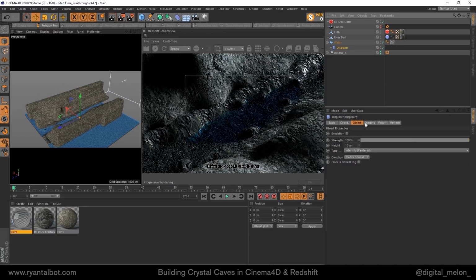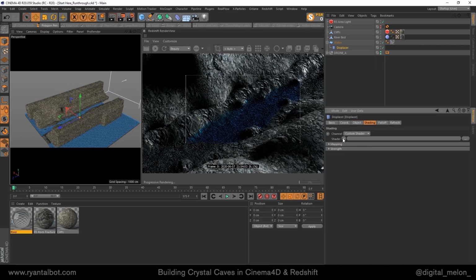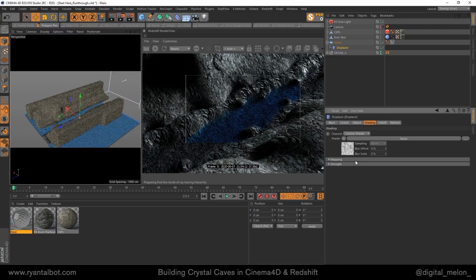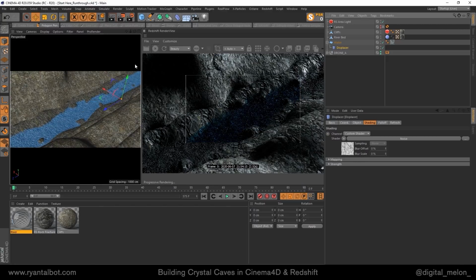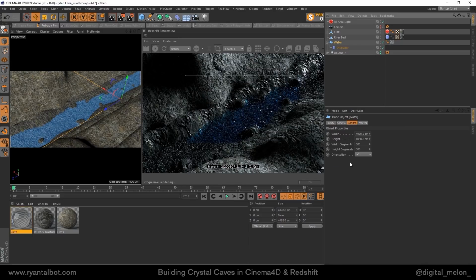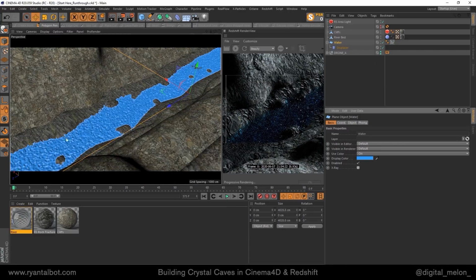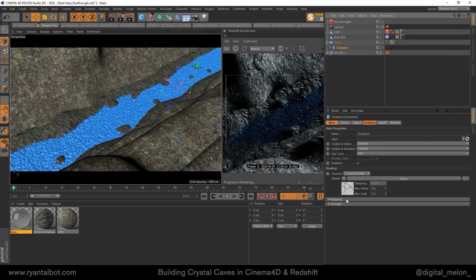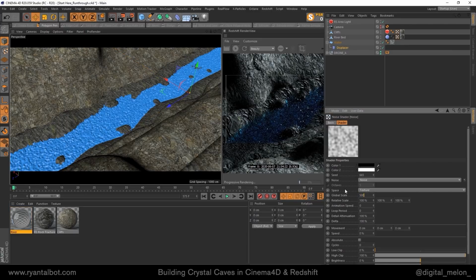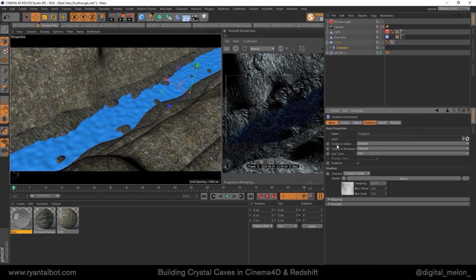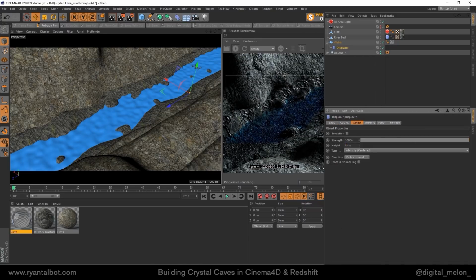And so this is a pretty simple and standard way to do some basic animation on your water. You essentially just drop a noise in here. And let me actually just jump into our camera so we can see that noise happening. And I'm actually going to turn off our X-ray mode so we can see this a little bit better. But that's what that's looking like right now. So what we need to do is turn up the scale of our noise, and that's going to give us something like that. And then what I did was I just changed the height to 5 centimeters to make that effect a little bit more subtle.